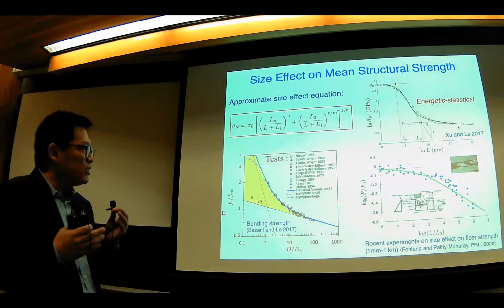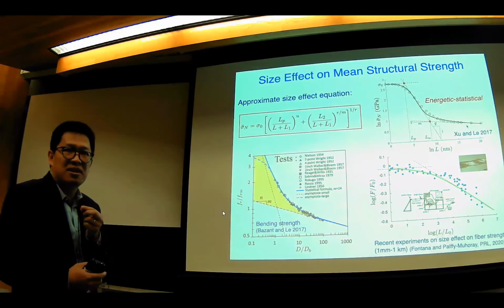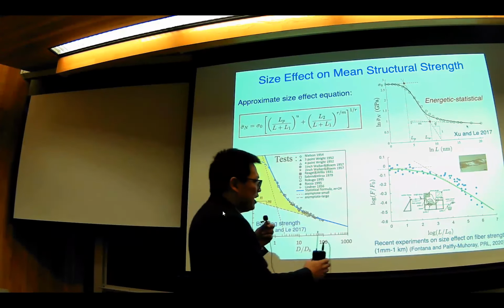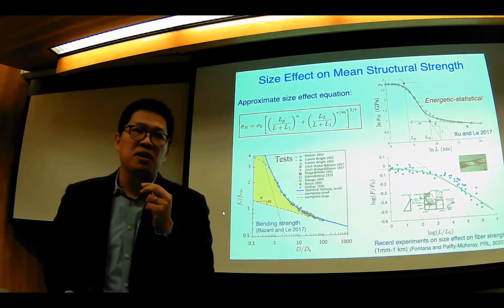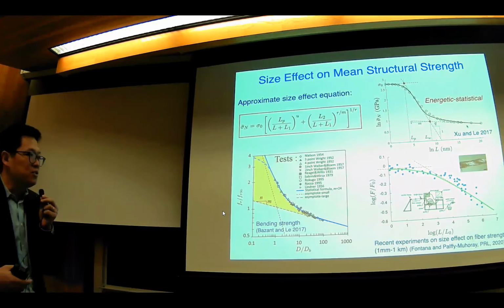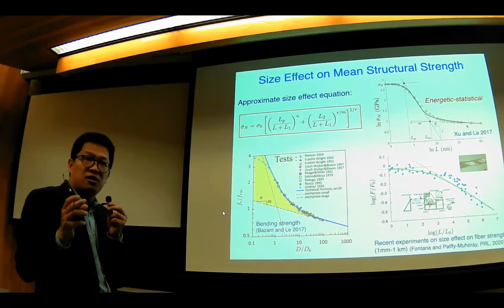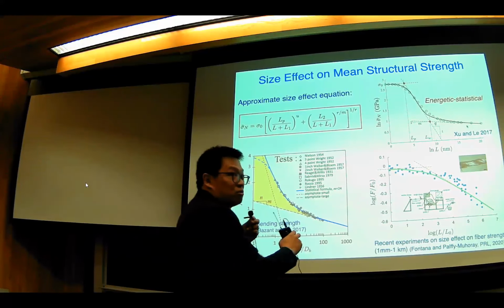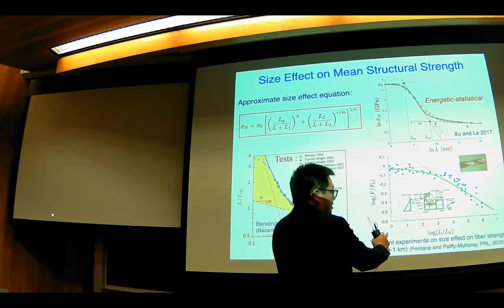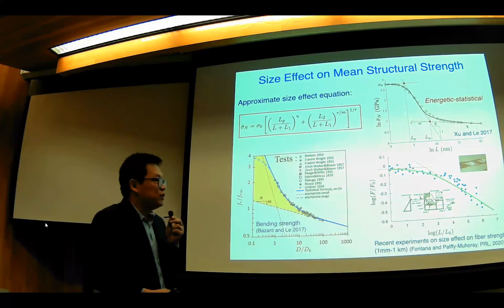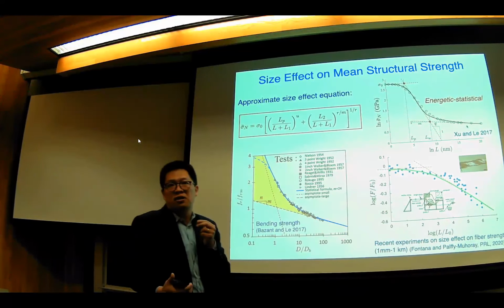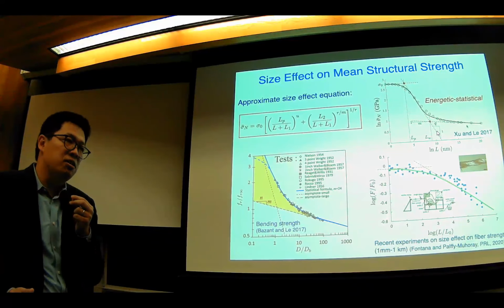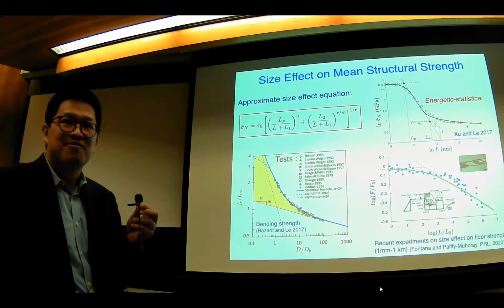But really, let's look at the order of magnitude in the size range. It's an enormous size range we are looking at. At the same time, I want to point out that the reason we have such a large size range, stopping somewhere here, is that the randomness in the system is really low, because you have a bundle of filaments. By the central limit theorem, you would expect the variation of a material property along the fiber to be pretty small. That's why you have a huge size range to drop the stress by this amount. If you test this in concrete, I'm pretty sure that within 4 orders of magnitude you will see the Weibull scale, because it depends on how much randomness you have in the model. So it's also very much material dependent. Yes.